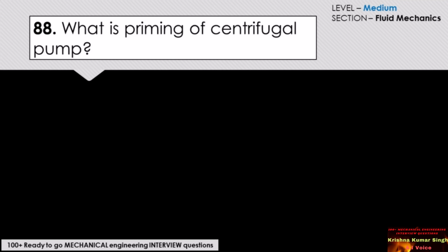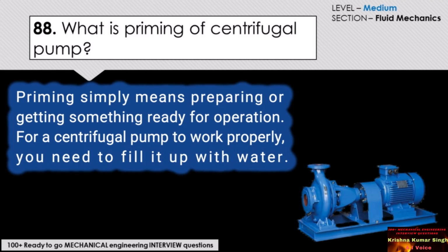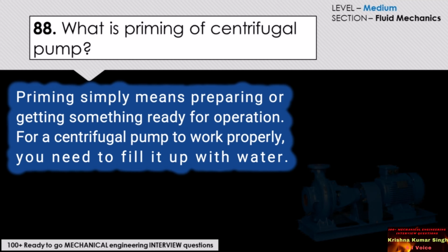What is priming of a centrifugal pump? Priming simply means preparing or getting something ready for operation. For a centrifugal pump to work properly, you need to fill it up with water. And this is what priming of a centrifugal pump is.